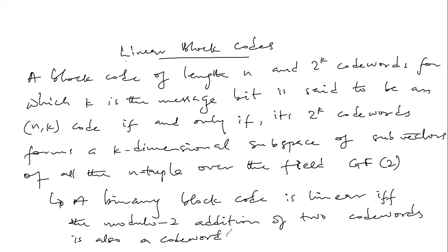So now, if that is clear, I will move on to what we described earlier. Should we have a code that is considered linear, since the sum of any two of its code words produces another code word, then we say that the property for which the modulo 2 addition of two code words forms another code word is called closure.